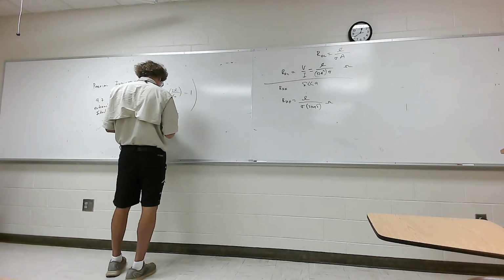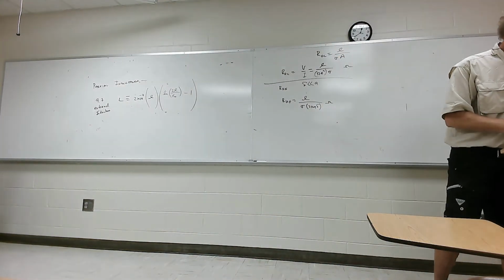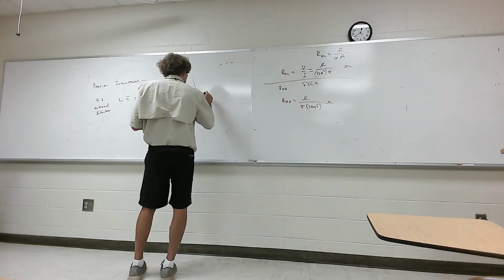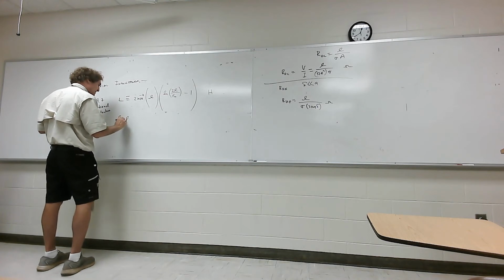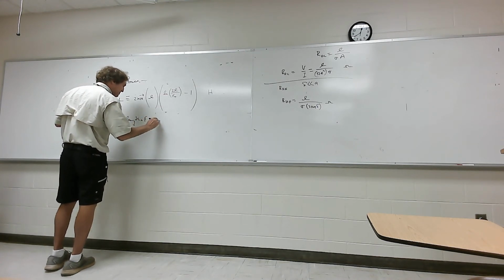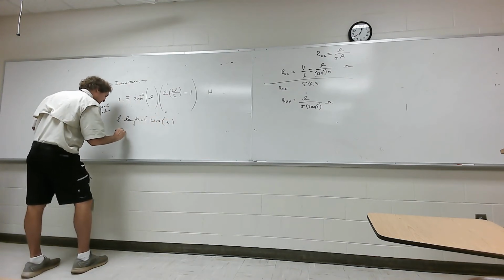Doesn't look like it came from anything. It was actually developed to approximate the value, and this would be in henries. Here L is the simple length of the wire, and it should be in meters, by the way. And the RW is the radius of the wire.